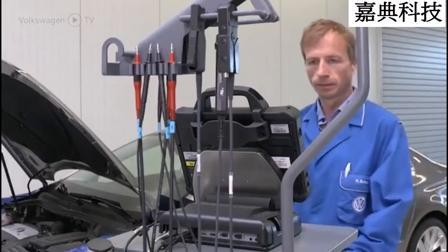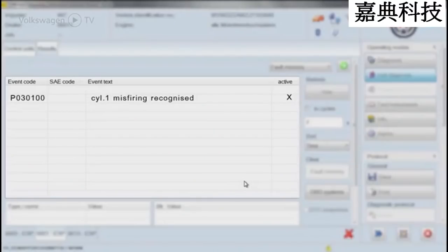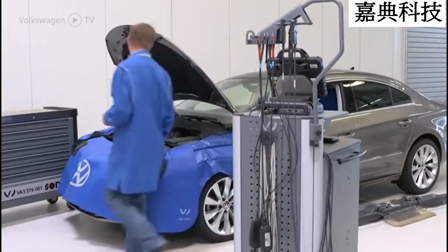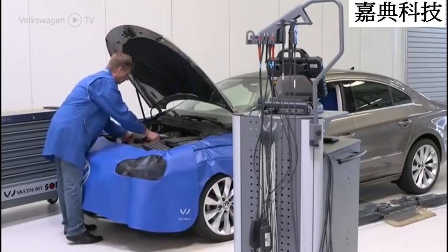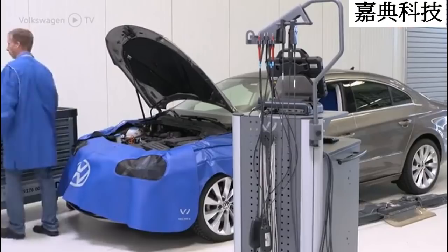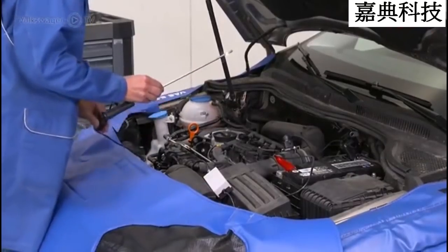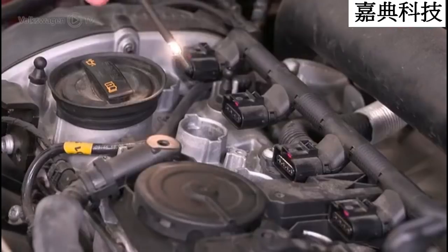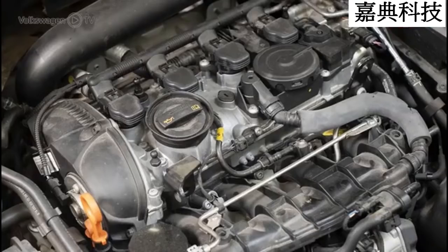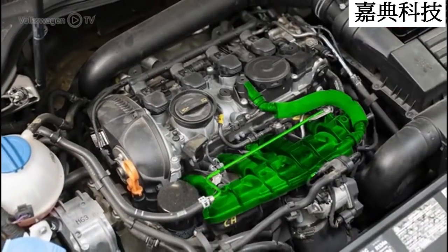To resolve the customer complaints, follow the instructions on the Vehicle Diagnostic Tester. After eliminating possible component faults, check whether there are deposits on the inlet valves or ducts. To do this, use a commercially available endoscope. Or, if necessary, try to obtain free access to the inlet valves.